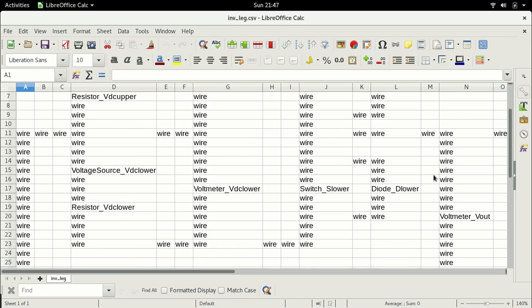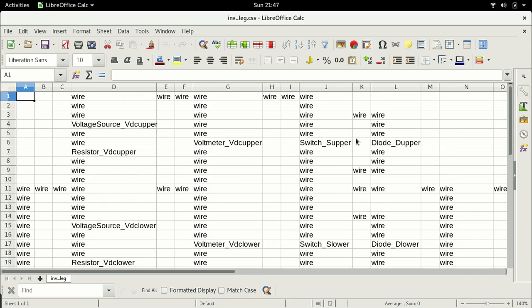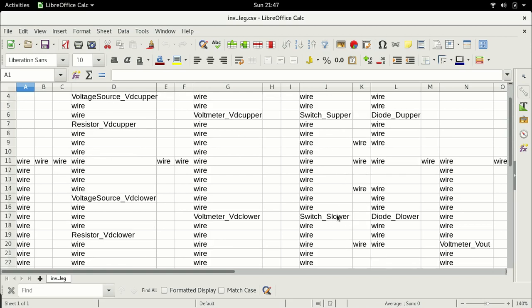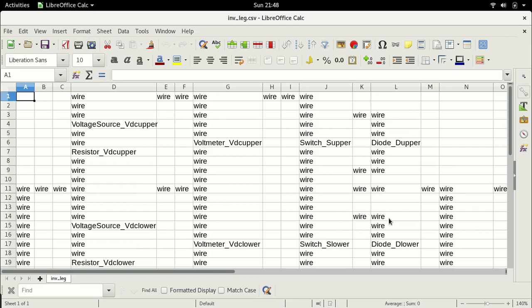voltage across this midpoint. So in the square wave modulation, we were keeping the upper switch on for the entire half cycle when the sinusoidal voltage was positive, and we were keeping the lower switch on for the entire half cycle when the sinusoidal reference waveform was negative. So basically there was a rectangular waveform, which is what I showed you last time. Now in this case I'm going to show you another way to simulate the circuit.